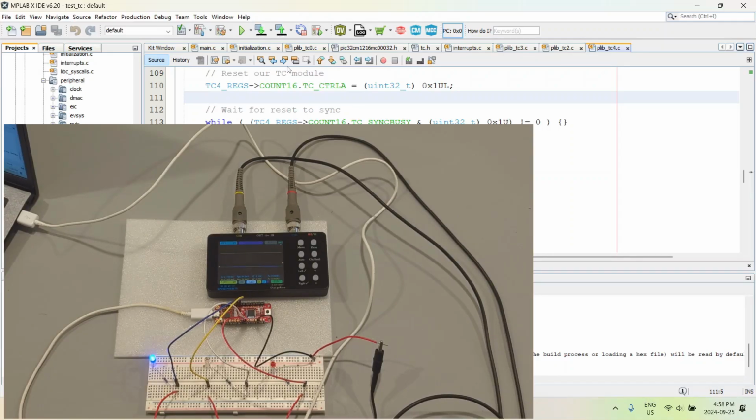So now what I'm going to do is zoom in on the oscilloscope, but I'm going to first check whether I am taking the correct measurement, because until now I had connected the oscilloscope and now you see the white LED has also started glowing. So therefore we have got our connections correct. Now I'm going to connect an oscilloscope probe to GPIO 11, or rather PA11, because that is what we are using as a 1 millisecond timer. So let me go and connect it there.